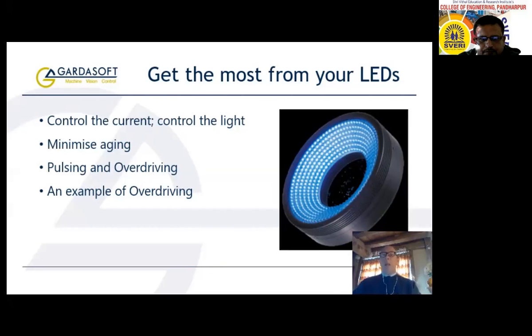While overdriving is a very powerful technique, it is necessary to ensure the LED is not driven at too high a current for too long, which may damage the light. Gardasoft has developed SafeSense technology to impose safe working limits on overdrive based on manufacturer specifications, pulse width, and duty cycle.